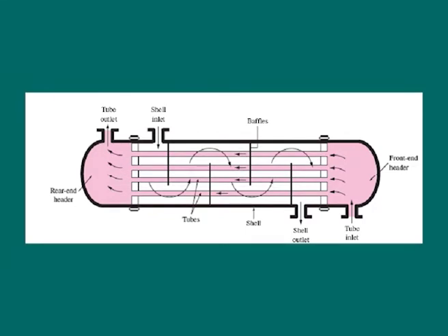Seeing the double pipe heat exchanger, this type of exchanger usually consists of two concentric pipes with the inner pipe plain or finned, as shown in the figure. One fluid flows in the inner pipe and the other fluid flows in the outer pipe in a counterflow direction. For an ideal case, the highest performance is given as the surface area is high. However, if the application requires an almost constant wall temperature, the fluids may flow in a parallel direction also. This is perhaps the simplest heat exchanger. Flow distribution is no problem and cleaning is done very easily by disassembly.